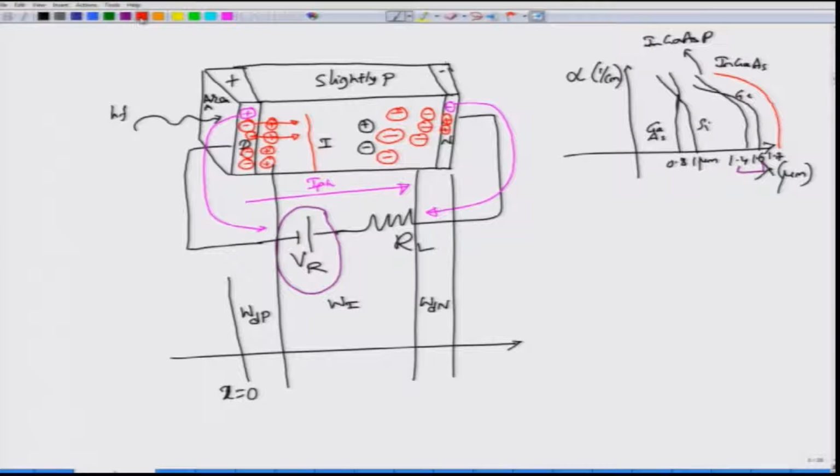The charge concentration, if you were to draw it, you will see that the p side region is characterized by heavy negative charges, because all the holes have flown through, and only the electrons are left behind. Similarly, for the N type region, you will see positive charges. Typically the N side is much more doped compared to the p side region. Therefore, the amount of charge which the N layer covers will be much larger than this one. So, this would be the charge concentration here. In between, there is a small negative channel kind of a thing. It is not exactly a channel, but it has negative charges.